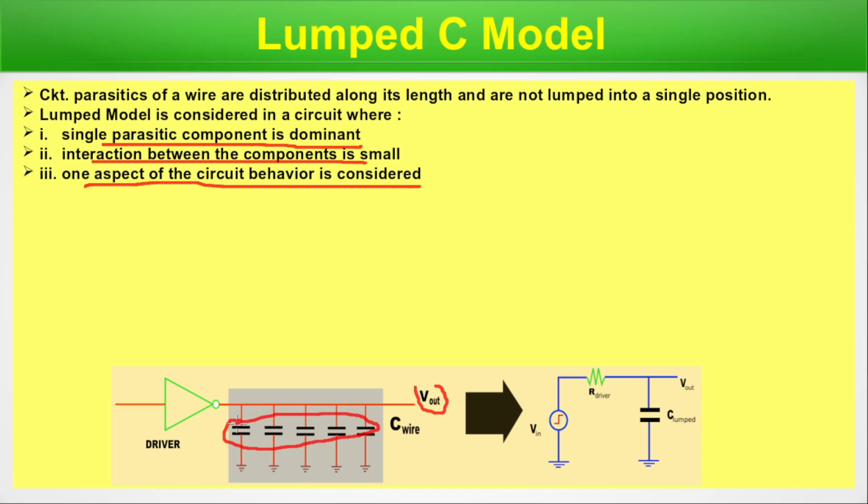In a more matured node, capacitive action is more predominant compared to the resistive parasitic. So there we can approximate that there is no resistance, only capacitive actions, which are modeled by some capacitance. So this is the driver and this is the V out. That scenario is modeled like this: this is the signal. Then when it's on, we consider it as a resistor, and altogether all capacitance values are lumped into one, and that is the V out. This is the easiest, the simplistic model.